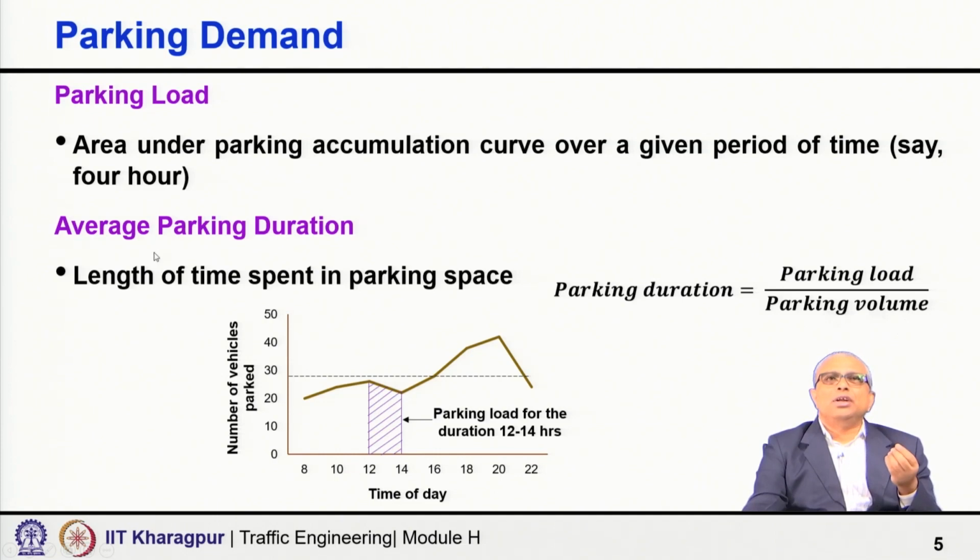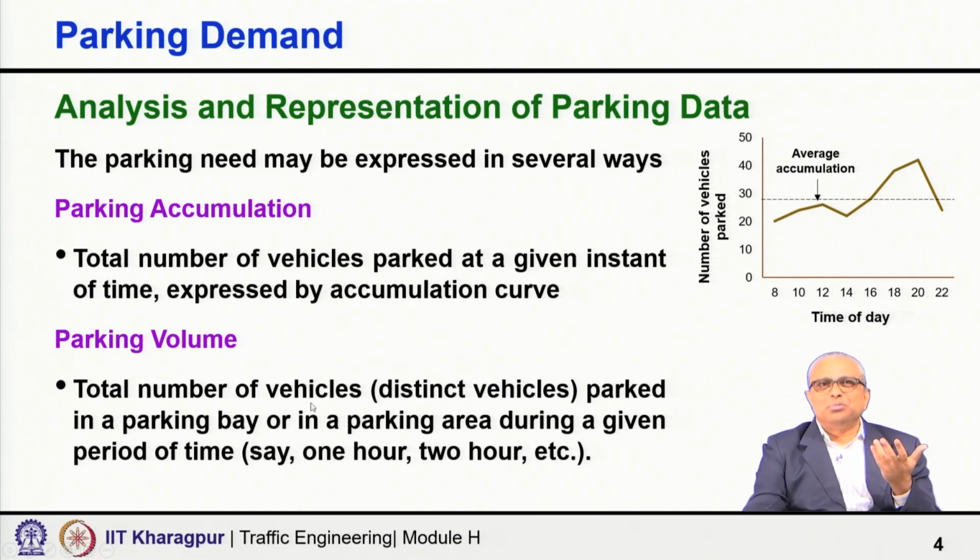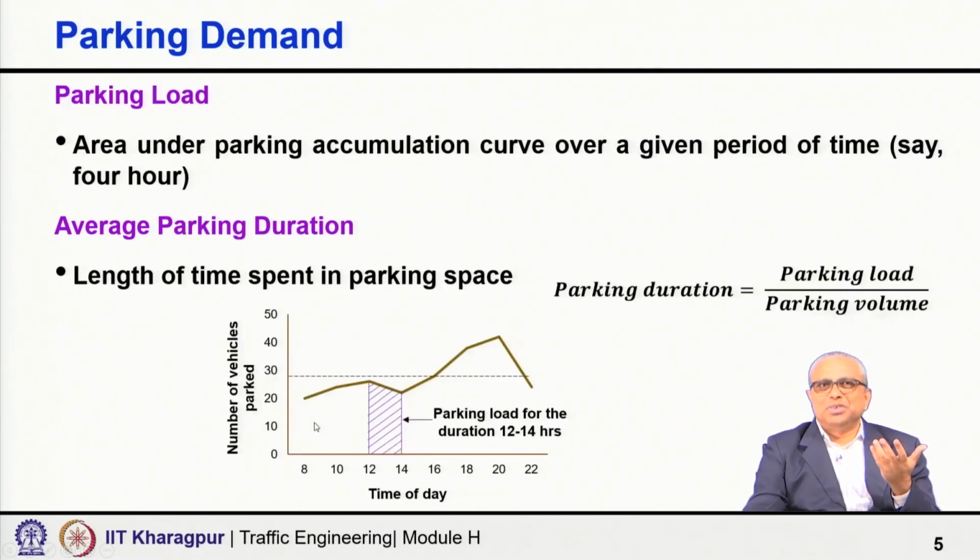Third, average parking duration. You can guess, right? I am sure you have already guessed how you can get it. How you can get it? Average parking duration: this area, that is the parking load. Parking load is nothing but this area, divided by the parking volume.